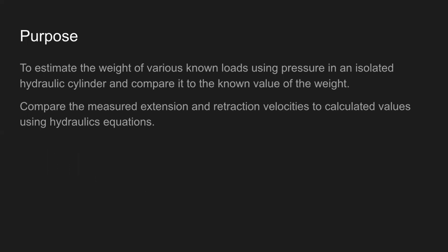The purpose of the lab was to estimate the weight of various known loads using the pressure in an isolated hydraulic cylinder on the excavator and compare that to the known value of the weight. We also wanted to compare the measured extension and retraction velocities to calculated values using hydraulics equations.